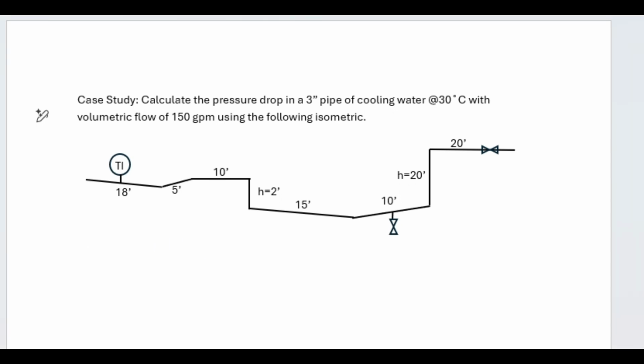So let's start by putting in density. Density of water, let's say 995 kilogram per meter cubed. You could verify that through a thermodynamic database or a property database, with the temperature. For densities of liquids,